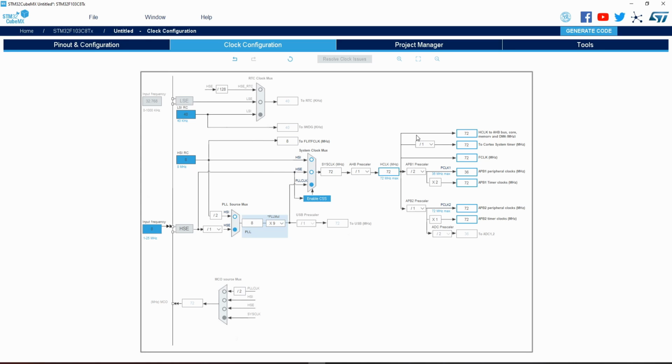So the input to the whole peripheral, as you can see in our configuration, is 72 megahertz. So the input to the whole peripherals, and then we go to APB1, and from APB1 there's a division here. We don't know, because if it was by 1, that will not be accepted and it will maybe destroy your microcontroller. So it's 2 here, minimum 2, and this is the APB1 peripheral clock. This is the maximum speed of the clock as an input to the peripherals for APB1.